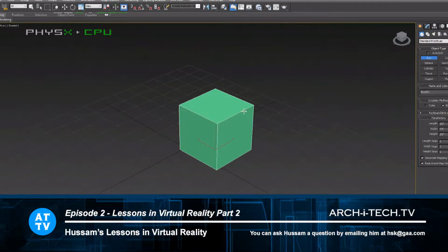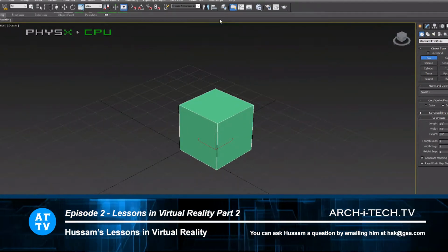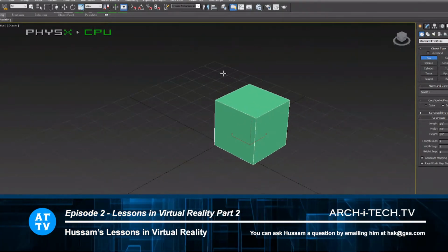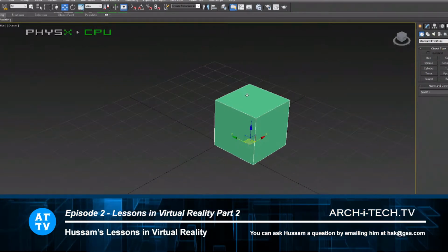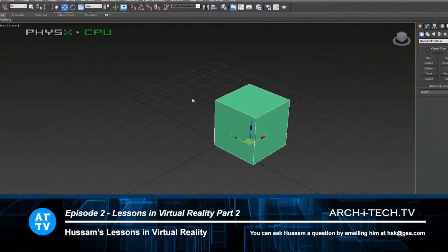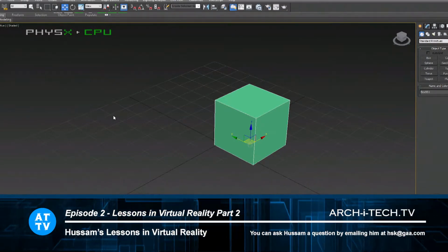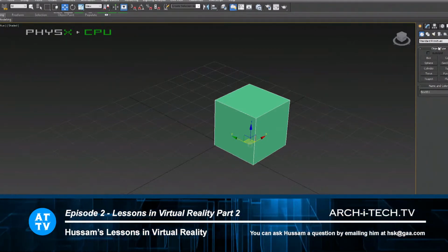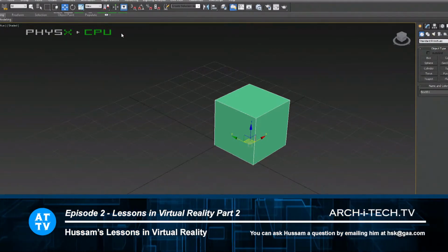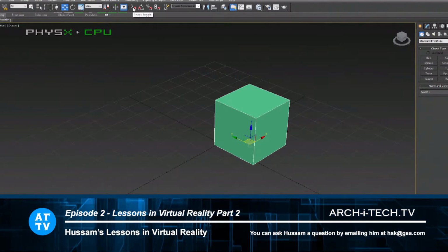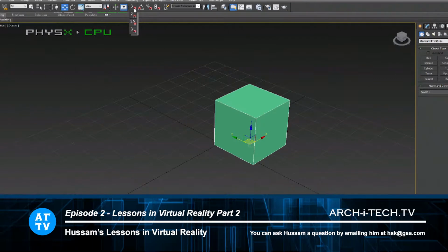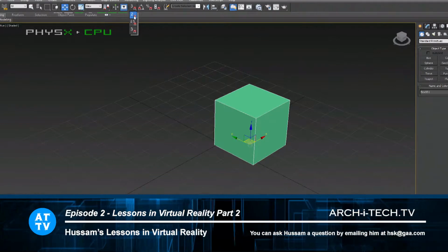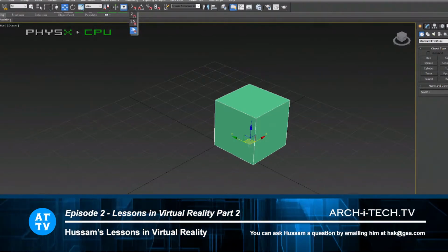So this is how you first start up with the unit setting and everything. And then the second important thing is the snap itself. For example, if you want to start snapping and redraw some drawing that came from AutoCAD, and you want to draw over them and snap in between the vertices, you have to go to snap over here in the main toolbar, click on it and keep pressing, and that will show you 3 other options, which are 2, 2.5, and 3.